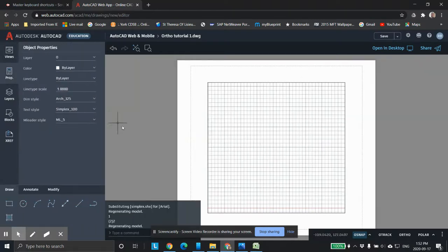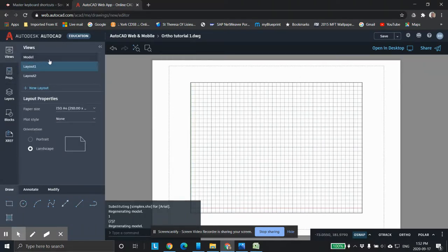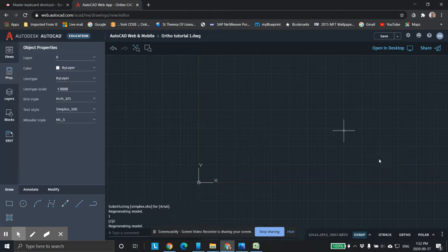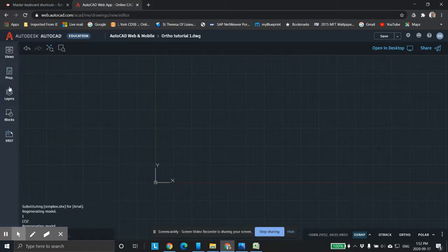So then you get into properties. Properties, let's go back into the model mode. Properties is if you draw something and say you're on one of the layers and you drew it all in the wrong format, dotted lines, or say you wanted to change the color, the line type or the thickness. You could come in here, you wouldn't have to redraw everything. You could come in here and change it. So you could select the layer and say, okay, select this layer and I want to change it all to this style. So that's where all that would take place.